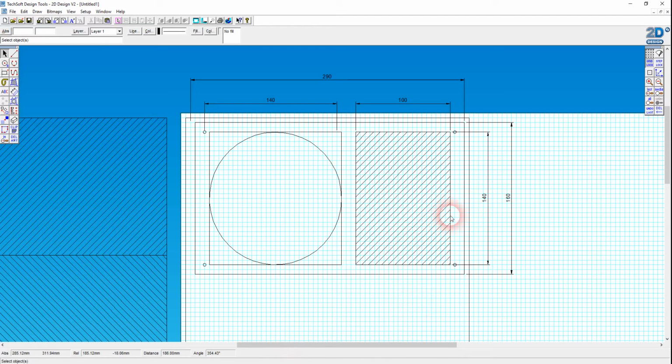my design. So I have my dimensions working out how big my product should be, but I noticed that some of these dimensions were slightly off because I moved things around a little bit last time and I didn't update the dimensions. So I'm going to select this top dimension here, which was the full width of the product, and you'll notice here that this no longer relates to the actual edge of my design. So I'm just going to select that. I'm going to bring it in just as 5mm, and notice that that dimension changes from 290 to 285, which